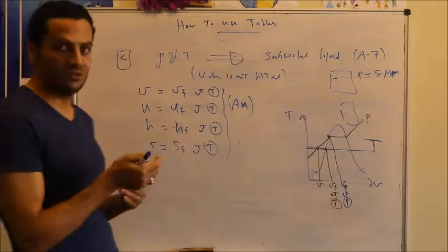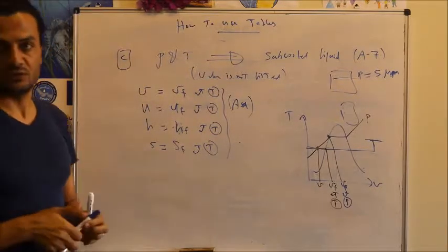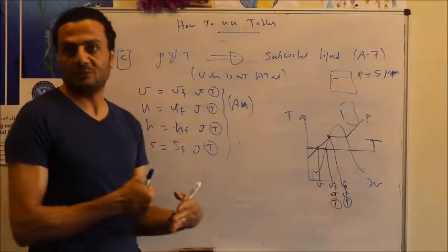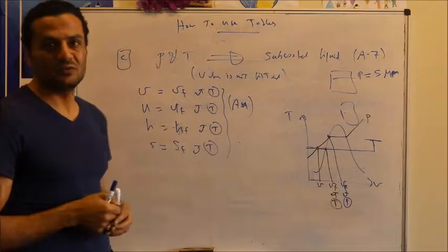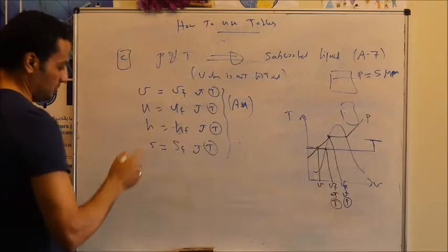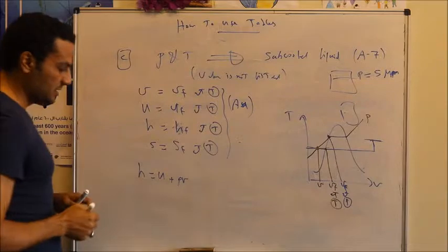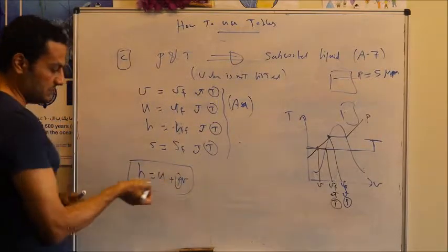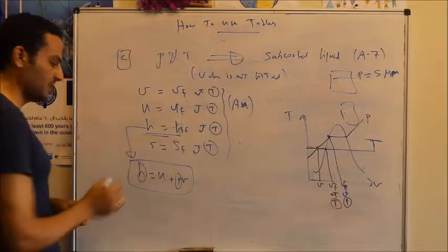But if you do have a change in temperature, any change in temperature will result in a change of the properties of those substances. So if you apply very high pressure on a liquid or subcooled liquid, the change of the properties will be very minor. But for a property like enthalpy, enthalpy is equal to internal energy plus flow energy, PV. So enthalpy is a function of pressure. If pressure is increasing, the enthalpy will change. So this means this assumption is not that accurate.